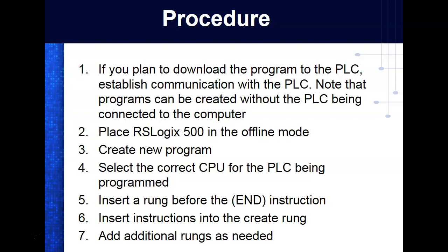No, we downloaded the PLC. That you got it. Yeah, I know, but that's the problem. When we download, we're used to getting something from the internet and bringing it to our computer. In PLCs, it's different because this is a computer too. The PLC thinks it's the big boy in the house. So we download, so we're acting like the internet. Where on the internet, you're downloading from the internet. Well, what we're doing, this is the guy right here. So we download into this PLC. So sending the information from your application to the PLC is a download. To get the program that's currently in your PLC into your application, that's an upload. So it's basically opposite of what we do on the internet, right?